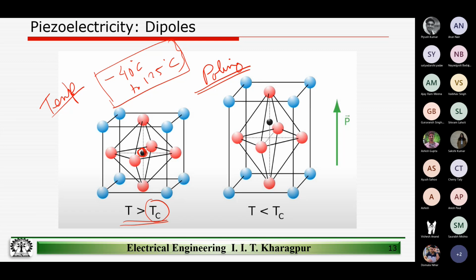And that becomes very important because, for example, here, this guy is a positively charged cation, right? That's what we discussed, right? So in this picture, for example, we have shown that this cation has moved above this particular plane, right? So in which direction do you think the Poling electric field would have been applied? That should be a pretty straightforward answer, right? Because it's a cation and this guy has moved upwards. So the Poling field must have been applied in this direction, right?